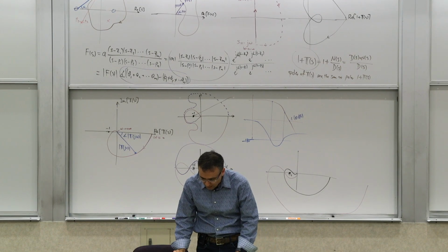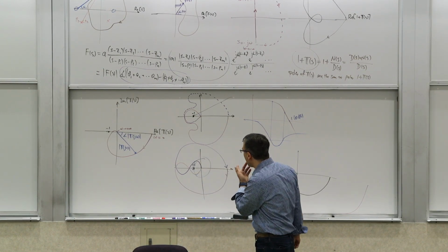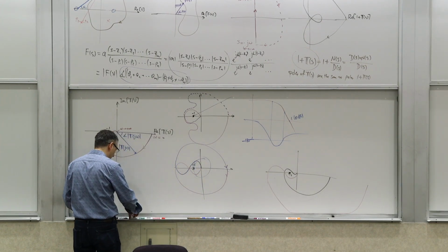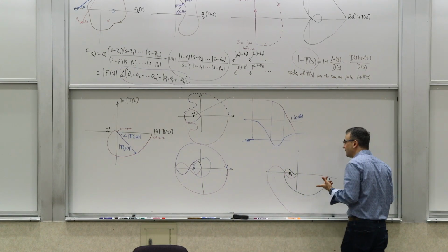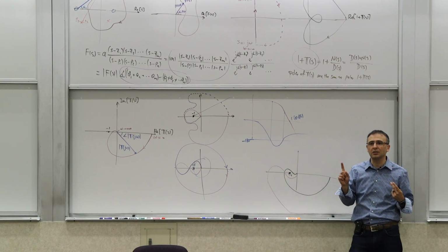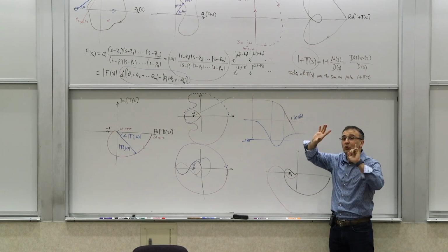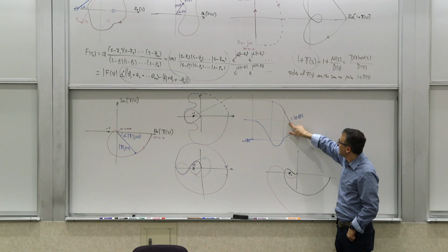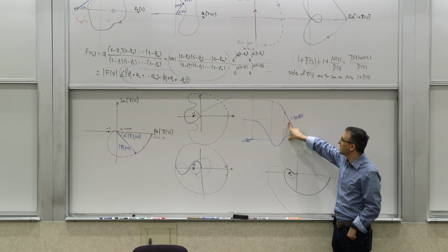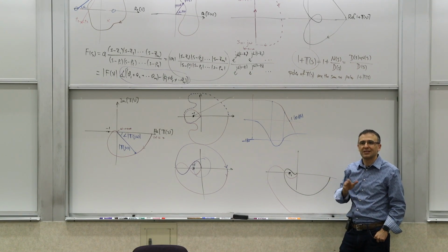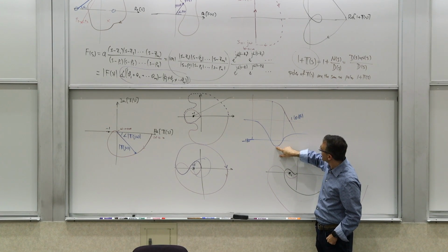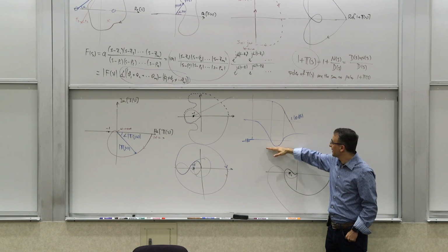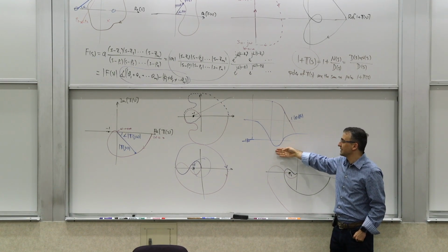that's basically an example of the Nyquist criterion. And if I look at these plots, you can also see what gain and phase margin are. We haven't explicitly talked about them, and we'll talk about them in a short while. But you can define gain and phase margin, and you can see that if you just blindly look at the gain and phase at a certain point, so if you were to define gain and phase margin only here, there, you would not be able to differentiate between them. So what is the phase and gain margin of this plot, for example? We haven't defined them formally, but if you just look at it, well, wait a second, this thing here goes under negative 1. So if you define it across the entire range, then you say, well, this has negative phase margin.